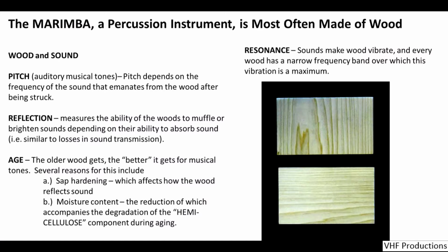The modulus of the material, or the stiffness of the bonding in the material, and the constituent properties of the composite are important. Woods are highly anisotropic with respect to their grain structure. When a tree grows, the grains of the tree grow along the length of the trunk, and so the wood has a very high aspect ratio between the grain structure and the direction the trunk grows versus orthogonal to it. The properties of wood are very dependent on the direction of that growth, parallel to the tree trunk or perpendicular to it. This is easy to demonstrate when you try to cut up wood.